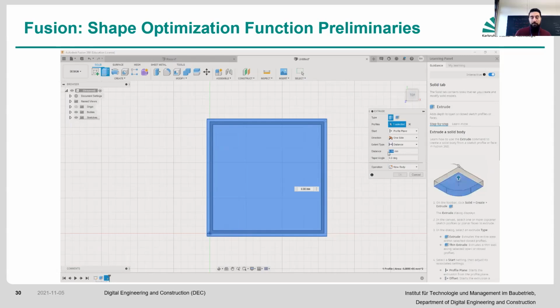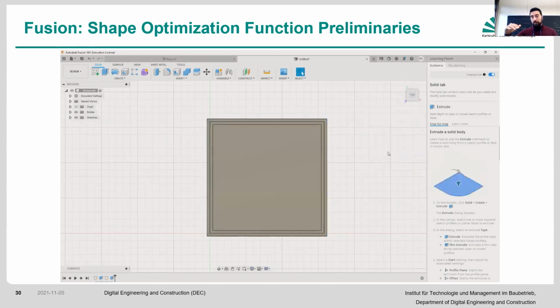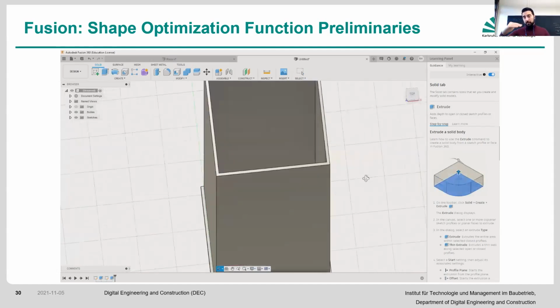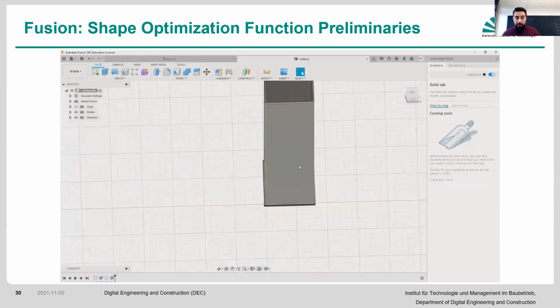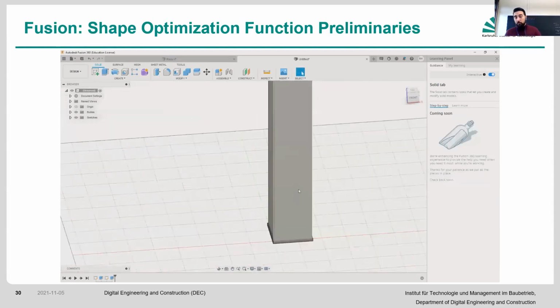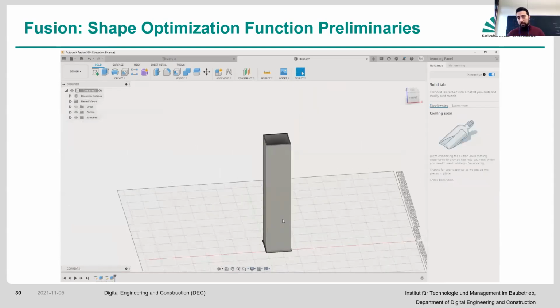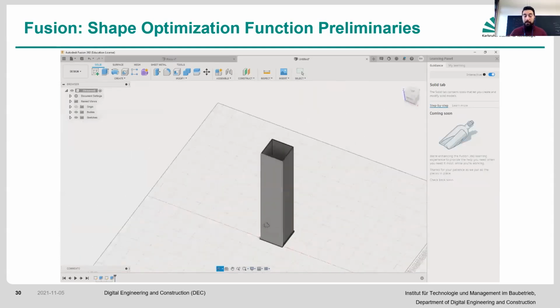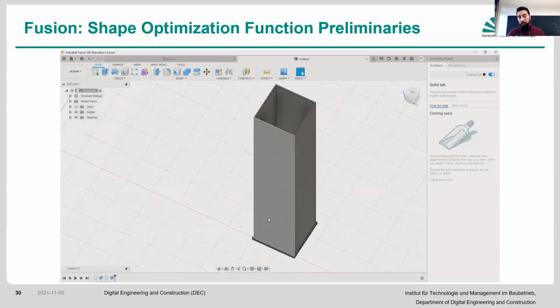This time, the good thing about Fusion is that if you do negatives, it understands it. So if your extrusion is positive, let's say 4,000, it goes up. If it's negative, it goes down. This is something that I did not find in Inventor, which was quite challenging, because you have to make sure that it is extruding in the proper direction.